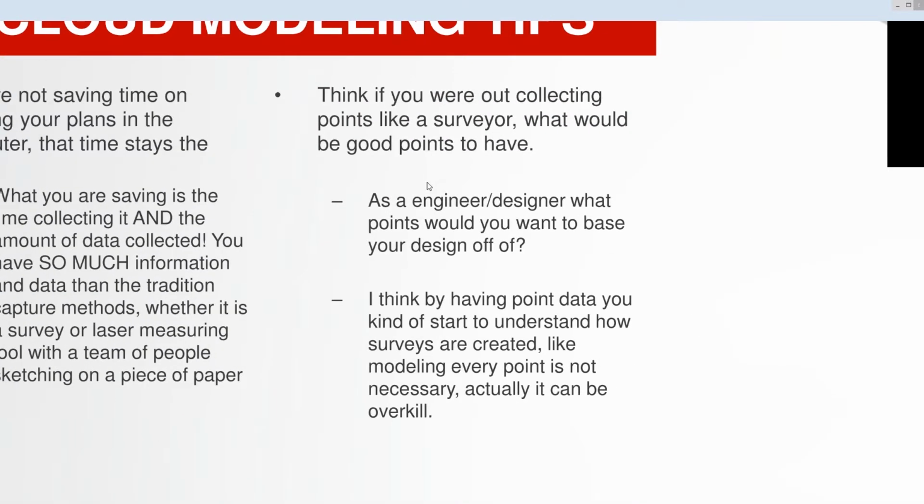You also have to think, when you're using a point cloud, that you have to be the surveyor in a sense, because you need to think of what's important to you as far as what points to grab where. Or you're the designer or the engineer. You need to figure out what you need to base your design off of. Those are the points you should be worried about grabbing on that point cloud. Don't think you need to model everything. It's just not that important. Surface terrains are a little different, but when you're just grabbing walls, windows, doors, curbs and ramps, you don't need every single point.